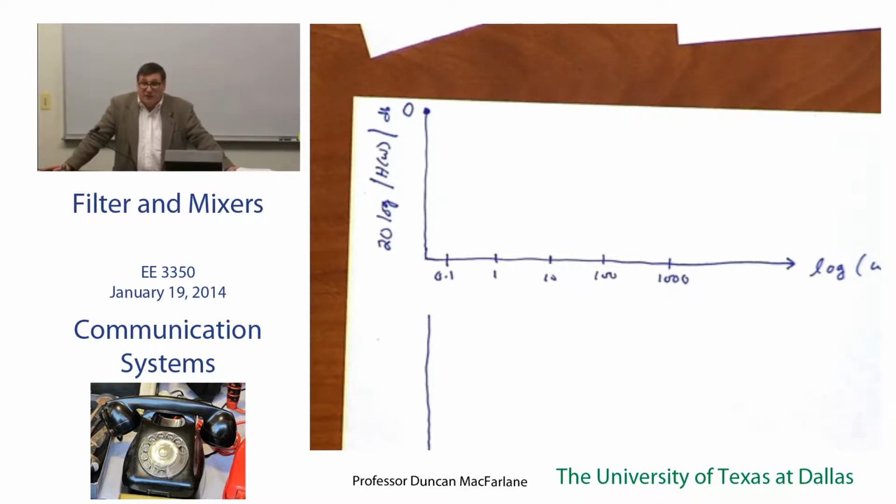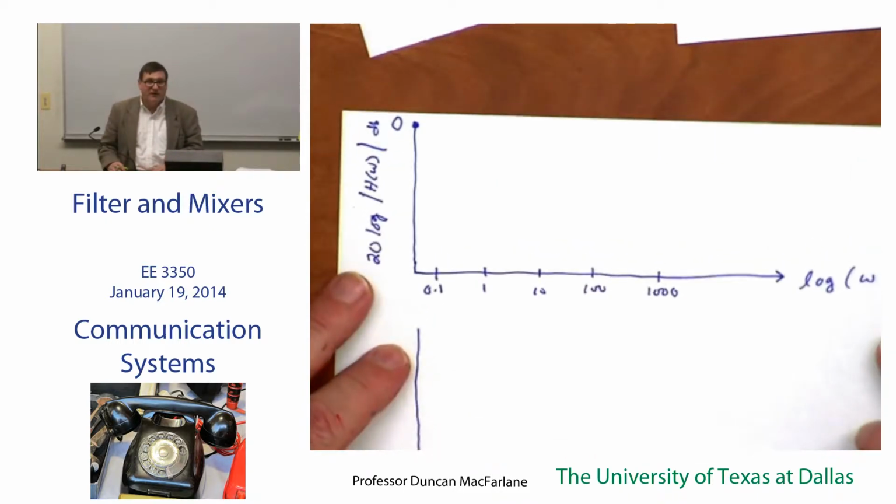Little d, capital B. If you take a look, the IEEE has probably 50 different dBs out there. I kid you not. But dBm is referenced to a milliwatt. A dBmV is measured to a millivolt. Regardless, we'll be sloppy and just consider 20 log like that.